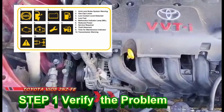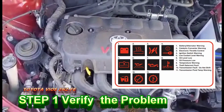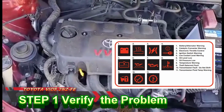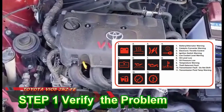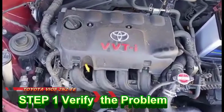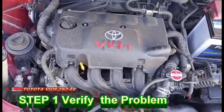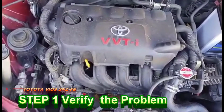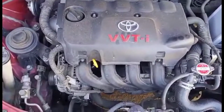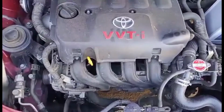Before diagnosis, always ask the following questions. Is the malfunction indicator light (check engine) on? What was the temperature outside? Was the engine warm or cold? Was the problem during starting, acceleration, cruise, or some other condition? How far had the vehicle been driven? Were any dash warning lights on? If so, which ones? Has there been any service or repair work performed on the vehicle lately? After the nature and scope of the problem are determined, the complaint should be verified before further diagnostic tests are performed.